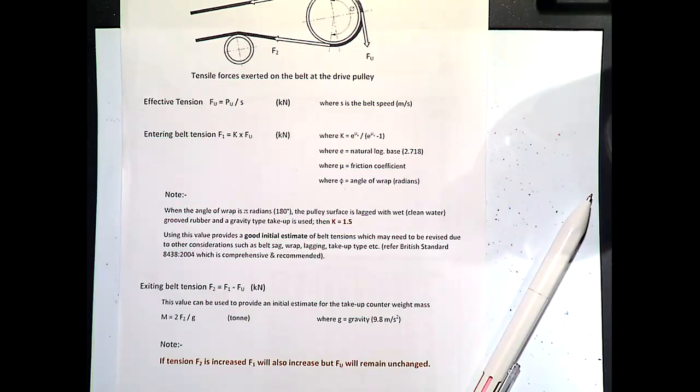Right, now for overland conveyors, the rolling indentation is one of the greatest resistances. They're doing a lot with these big distance conveyors to try and overcome this. When you look along, you can see the indentation. That's empty, all the way through.